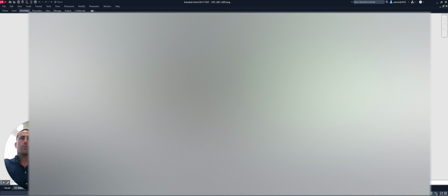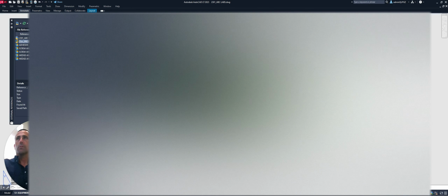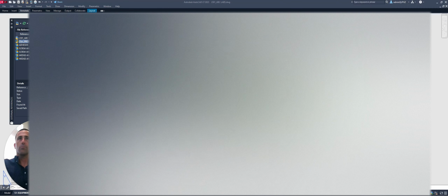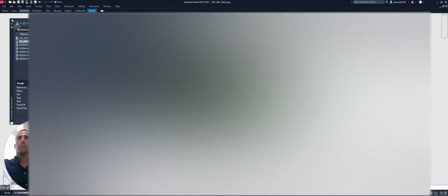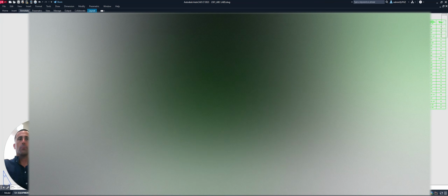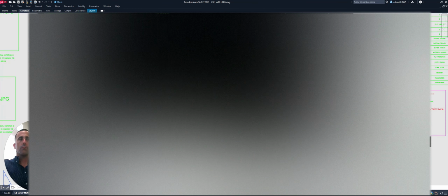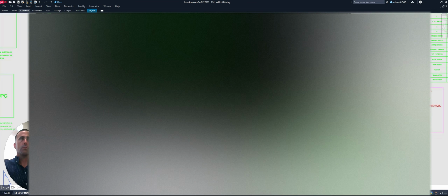So you can see here the first thing it prompts me for is to reload my XREF file, my border. So I'm going to say open XREF palette. So I'm going to come over here to that border file. I'm going to select new path. And I want it to come to 23, example projects, ABC Labs, plans CAD, original CAD files, 2301 border. There's the border file. So we have our border attached, we have the sheet name, equipment Anchorage, we have the sheet number S1, and